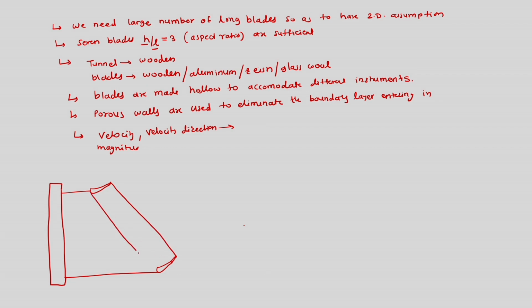and we know that this is called the cascade, and here we would see this is an upstream traverse probe. This probe would have sensors mounted before the cascade. So this is the velocity, which is Cx1.